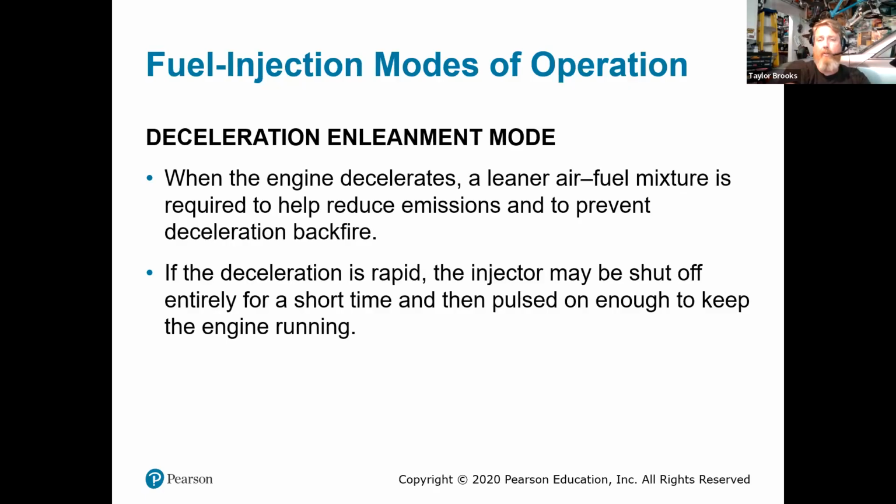The last thing we're going to do, well, second to last thing I should say, is going to be deceleration. And this is basically going to reduce the fuel being given to the injector so that we can naturally slow the vehicle down. What this allows for is the computer to have the ability to reduce the pulse width or shut the fuel injectors off entirely, and allows the engine to basically decelerate.